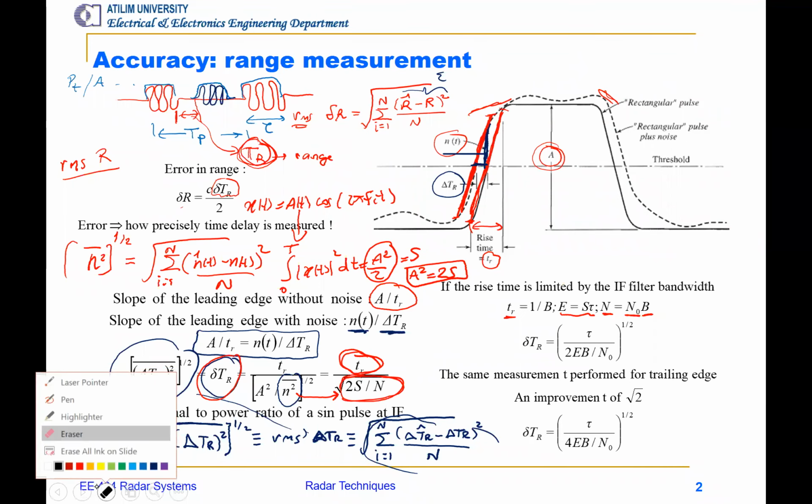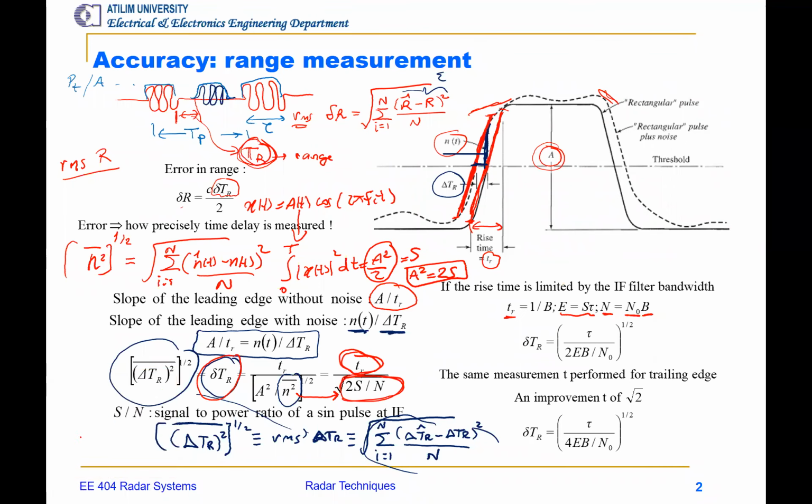The radar receiver, how to measure this TR. From the antenna, simply we have an LNA at the radar receiver, we know it, and then a mixer, okay? And then we have an IF stage, which is a filter with an amplifier, we say. The received signal has a frequency, let's say FRF.